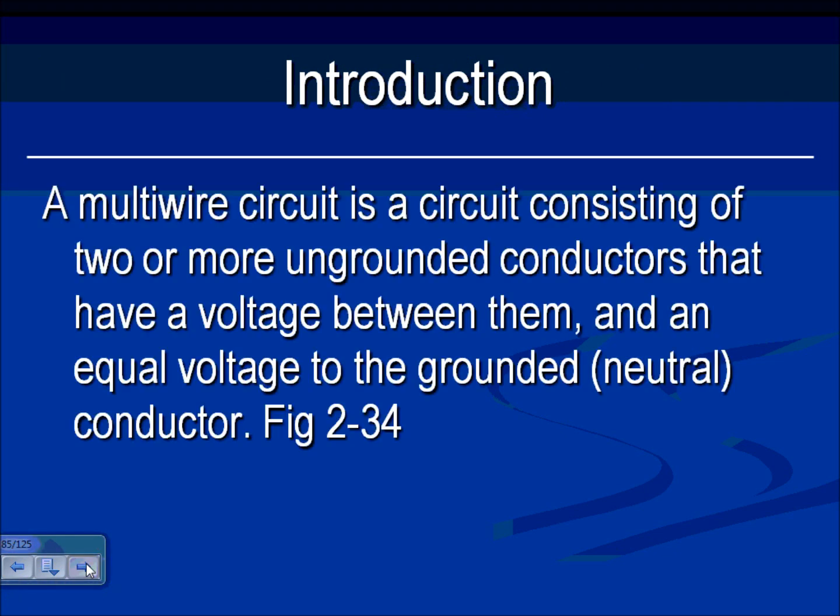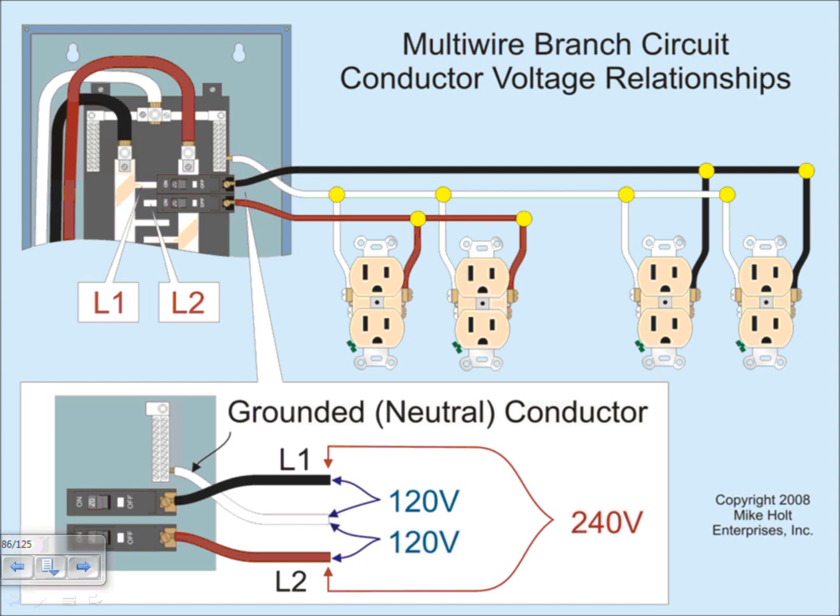Okay, I'm going to go directly now into the multi-wire branch circuit, aka polygamy, like Chad said yesterday. A multi-wire branch circuit, guys, is when, as you can see, everything is in parallel. I want you to understand that all the loads are connected in parallel, except you're utilizing two voltages. One line of voltage is coming here, and a second line of voltage is coming from the other top. But they are all going to the same reference.